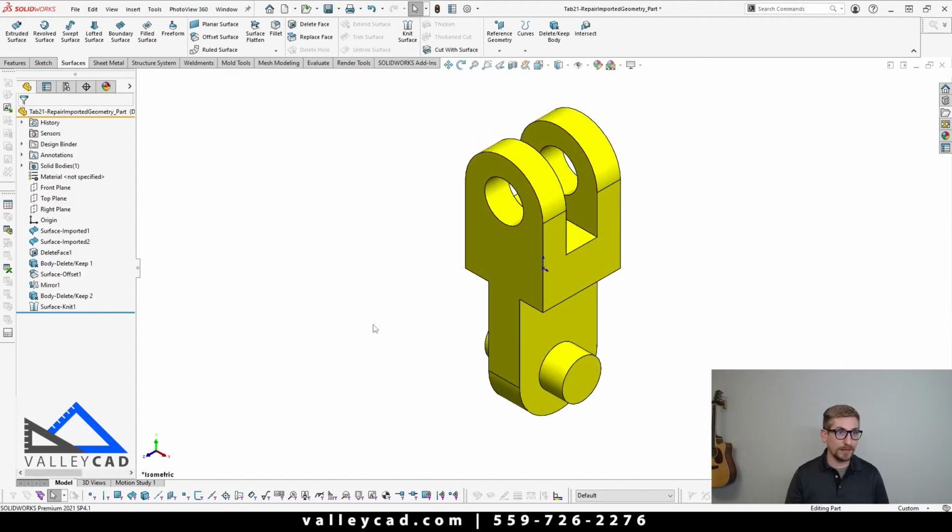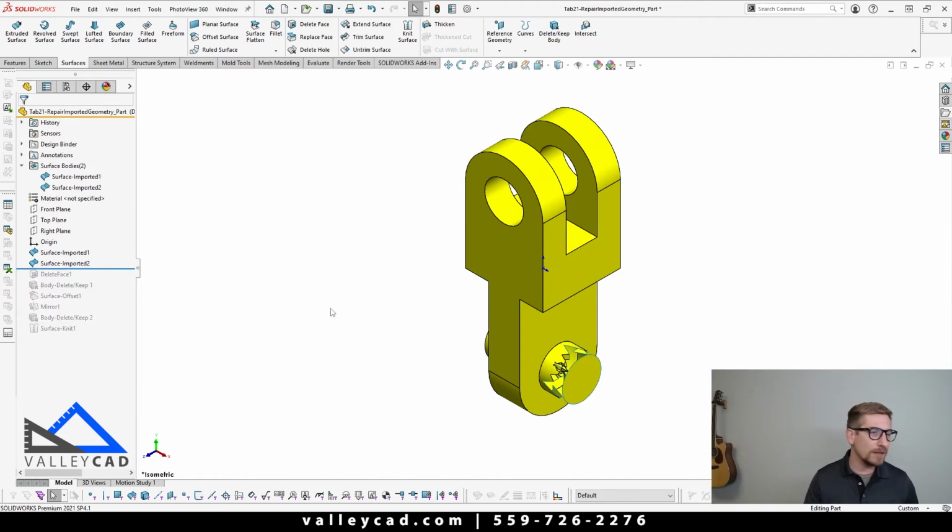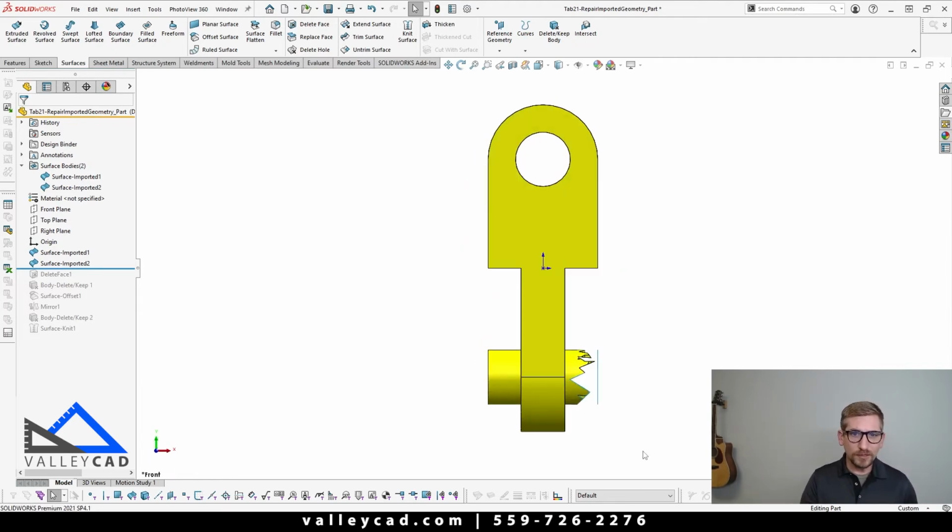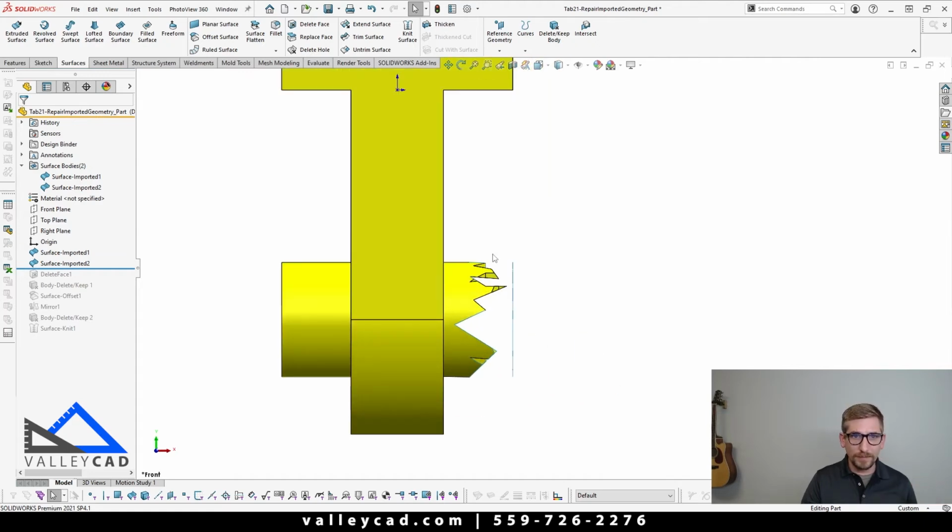And now we'll be coming in and creating a solid geometry like so. Not too shabby, right? But let's look at another way that we can make this work. I'm just gonna use my rollback bar to go back in time to show how this looked when I first imported it. All right, so looking at this here, that delete face command that we used originally, yeah, that works, but I'd rather come in and do something a little bit easier than that.